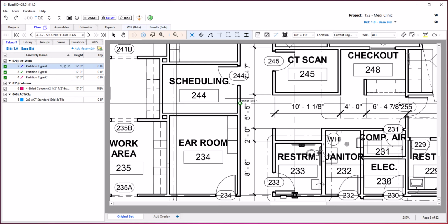In this case, I'm going to settle over the 3 5/8 wall. Now that I've selected that, I can count other 3 5/8 walls with one click like this. Anytime I move the cursor over it, I'm not pressing the key in any way, it highlights that, showing what it's going to count if I click it once. If I do click this wall, it stays selected. You'll notice that once I've locked onto the 3 5/8 walls, I can move over the 8-inch walls and it cannot see this wall over here.